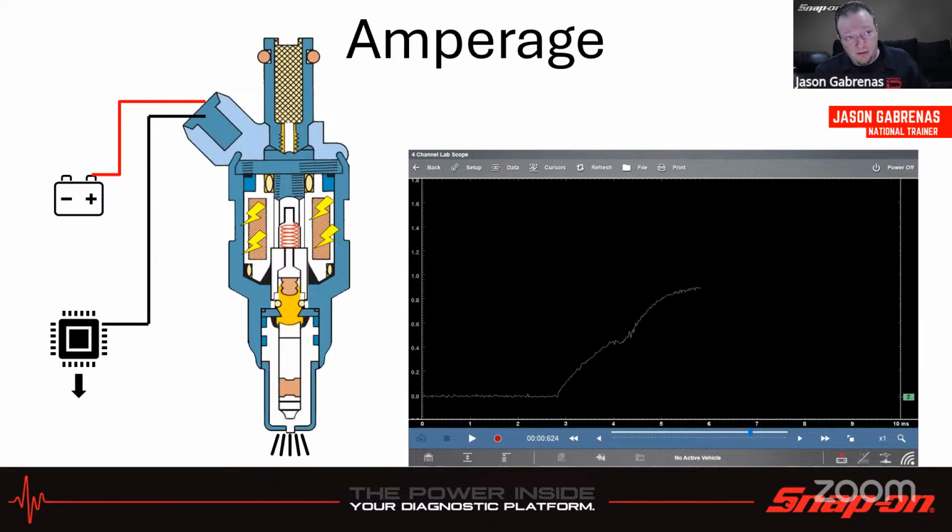So we'll have a little bit lower amperage that needs to be to overcome that resistance in that case. Now you want to keep an eye on that. If you're watching a single injector and you're testing it, you want to make sure it's opening at roughly the same point every time, as long as the RPM's the same. If it's being really erratic, you might have a broken spring in there. It's just not opening and closing at the same rate every time. So most likely a mechanical issue inside the injector.